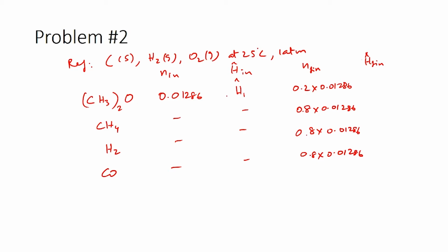So, there is definitely a change in enthalpy here. So, what about the dimethyl ether enthalpy for the final condition? Here the pressure is different, however, the temperature is still the same because it is an isothermal process, which means the enthalpy would still be the same because we are going to ignore the effect of pressure for an ideal gas.